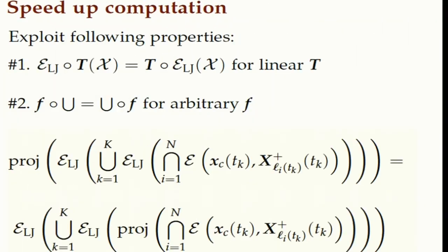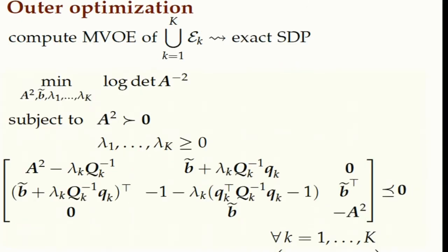Now, as you can realize, because of the high-dimensional nature of the dynamics, each of these matrices has the dimension of the state space, so 12 by 12. Because of symmetry, we gain something, but still it is a high-dimensional optimization problem, and there are a lot of LMIs for each time. So these are really high-dimensional semi-definite programming problems.